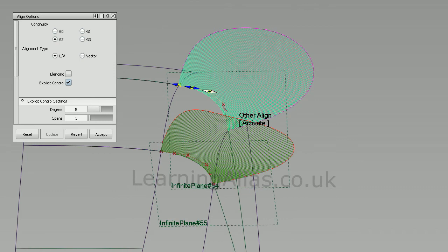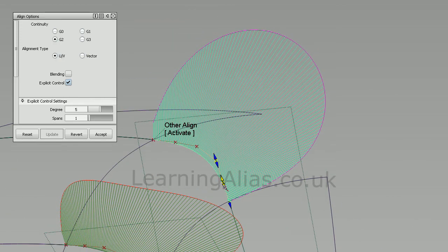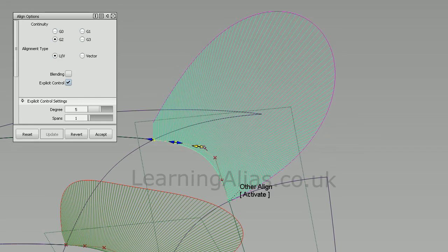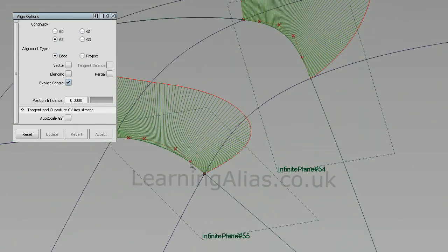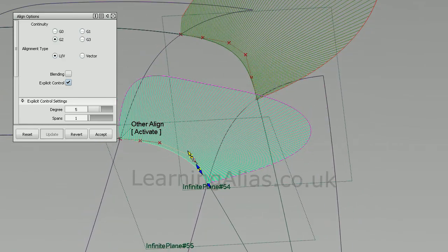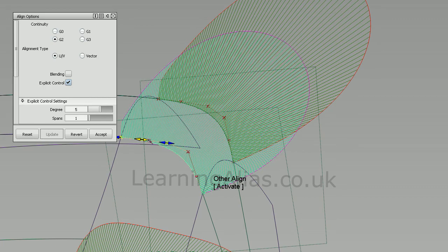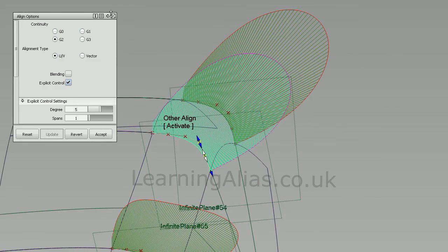So using the align tool, you can click on the curve and it will re-invoke the history, and you can tweak the curve to get a much better, much more even and a nicer crown on our comb. Try and remember what you're doing to each CV, because obviously we're going to have to repeat this with all the other curves, and you want them to correspond to one another so that the CVs line up. So we know we need to slide these guys up and these guys out. And we're slowly matching the first curve that we did.